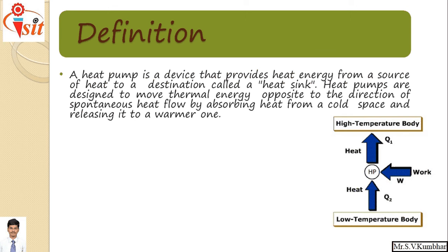So in heat pump, in this figure, heat is continuously extracted from the low temperature body. That heat is supplied to the high temperature body, provided that the temperature of the high temperature body is kept at a high temperature. For that purpose, we have to supply work to the heat pump. Heat pumps are designed to move thermal energy opposite to the direction of spontaneous heat flow by absorbing heat from a cold space and releasing it to a warmer one.